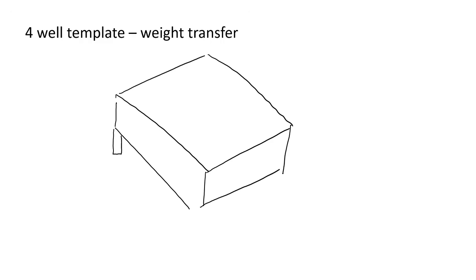Let's say this is a four-well. These piles that are supporting the weight of the manifold are typically suction anchors. If you don't remember what they were, we have the soil, here we have some fluid, and then we have a pump that sucks the liquid out. This creates a negative pressure, and then the anchor simply will be driven down.